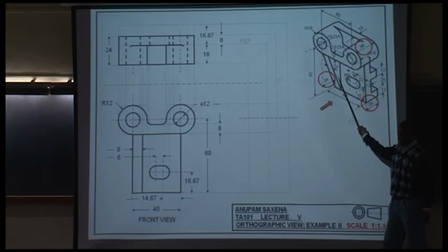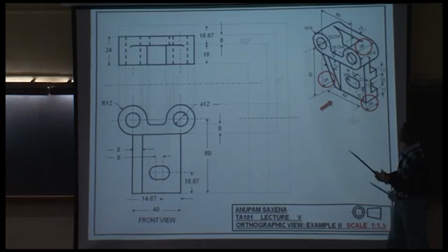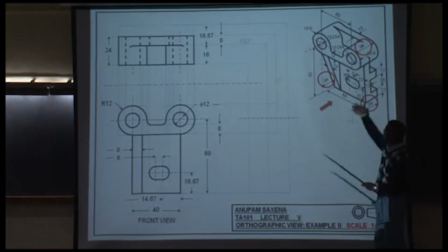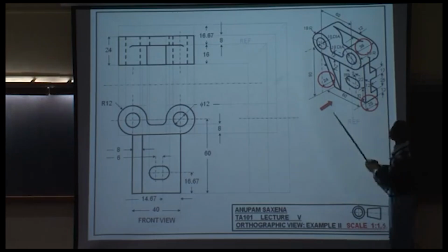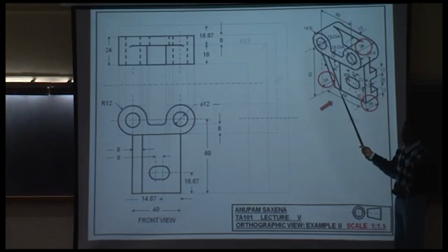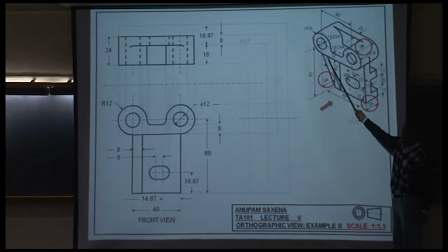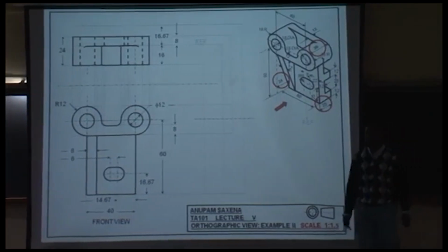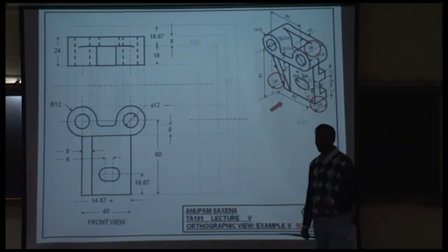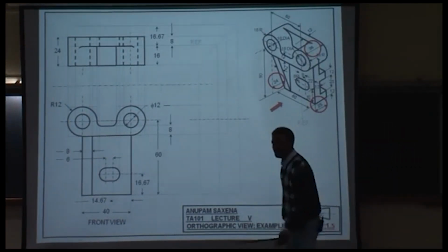So this is like a tapered rib. It is glued to the reference plane. Here the thickness of this rib is 0, and here the thickness is 24. Is it scaled or unscaled? Unscaled. So 2/3 of that is 16.